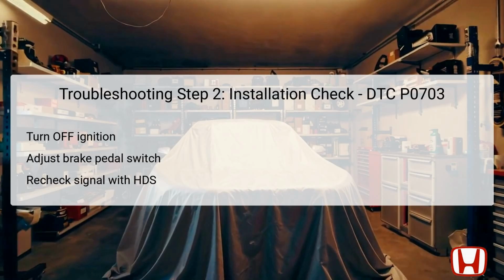Once adjustments are complete, turn the vehicle back to the on mode and again check the brake switch signal using the Honda Diagnostic System, HDS, without pressing the pedal. Confirm whether the current conditions now match the expected threshold. If they do, the failure may no longer be present, and you can conclude the troubleshooting. If not, it will be necessary to move forward to Step 3, as a methodical approach to locating the issue is essential.